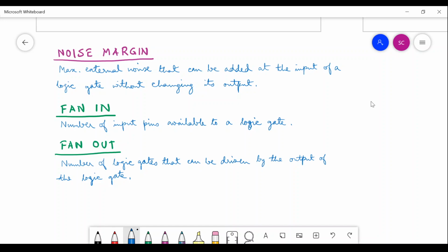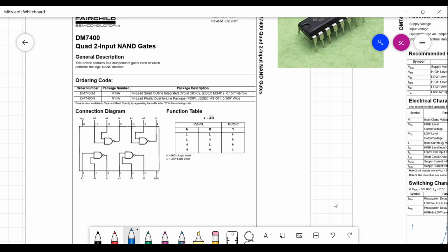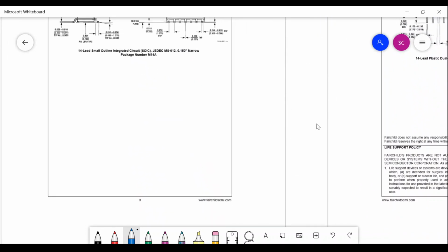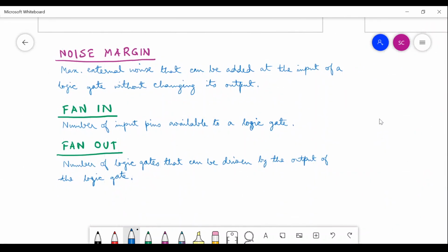So this particular manufacturer, this Fairchild, has manufactured this NAND gate IC chip, and their propagation delay times we noted as 22 and 15. Some other manufacturer may supply a lesser propagation delay time, it can so happen. So one has to know all this by reading the data sheet and choose wisely which manufacturer to go with. So all these things are there.